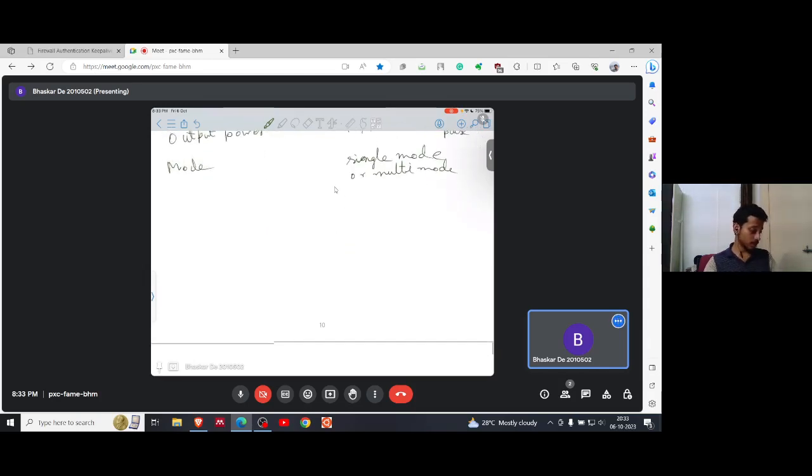Okay, so now the application of this Nd laser has more different kinds of application than any other type of laser. Nd laser is the most commonly used laser basically. Perhaps the major application is in various forms of material processing, drilling, spot welding and laser marking, because these lasers can be focused to a very small spot.